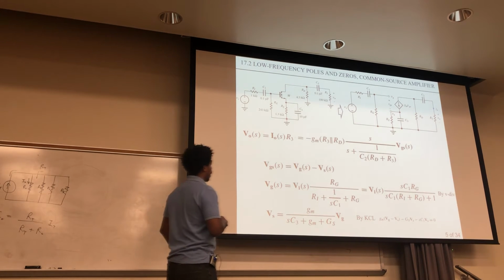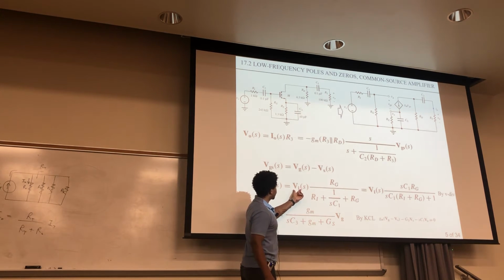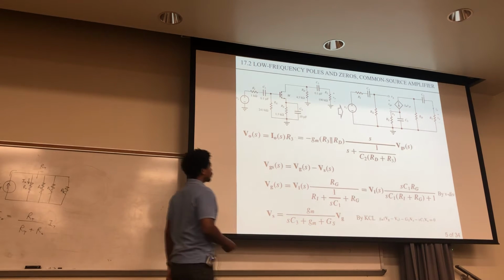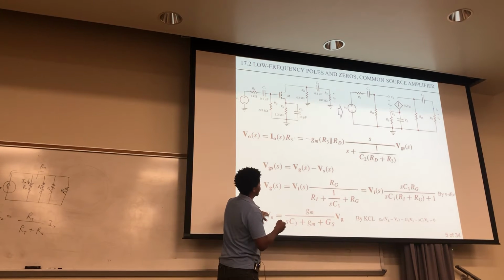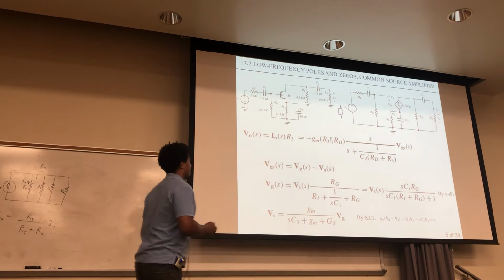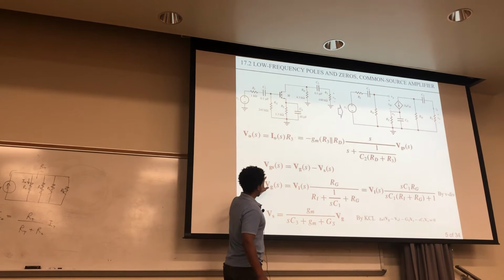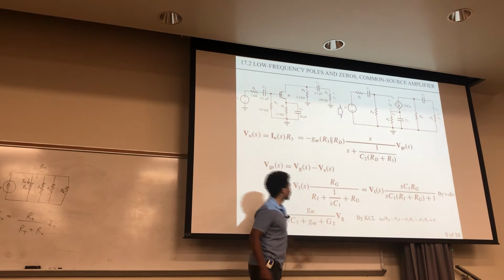And the voltage at VG is found by voltage division. Unfortunately, it's in terms of VI. That's actually something we want, because we want to figure out what the gain is, which is output over input. So that's going to be over that input right there. So we did that by voltage division, and we did this by KCL to find out what VS is. And we had taken those values, we had taken this, plugged it into there, and taken this, plugged it into here and here.